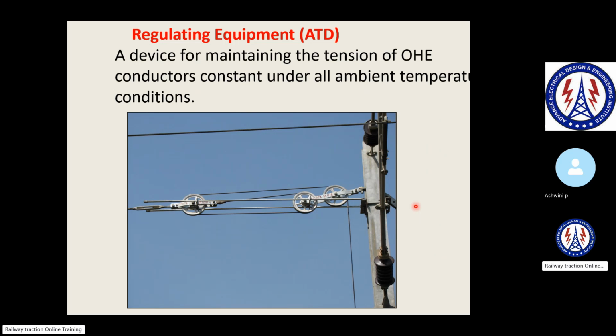So this is how the ATD works. It is an auto tensioning device, a device for maintaining the tension of the OHE conductor constant under all ambient temperature conditions. When the temperature increases or reduces, this